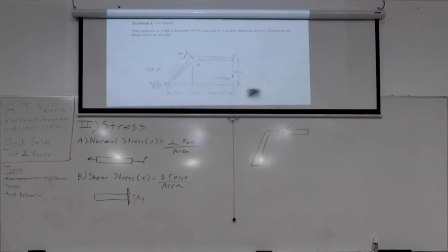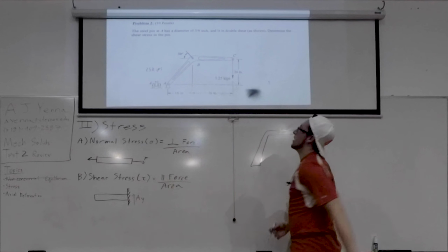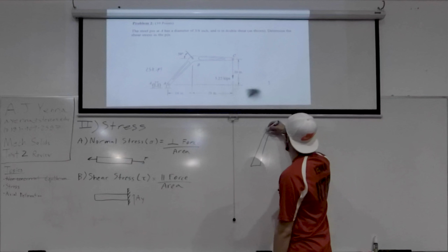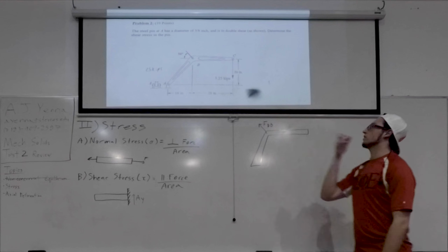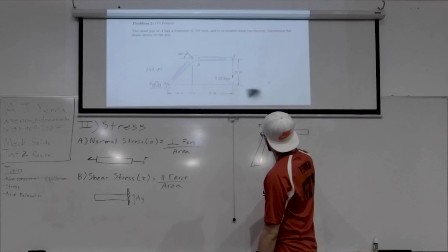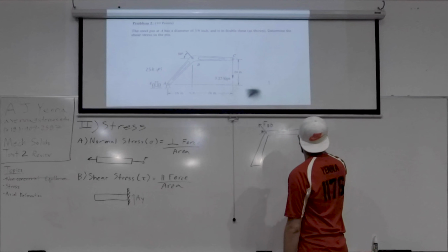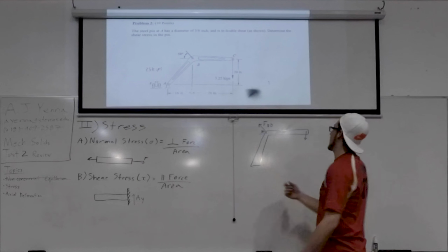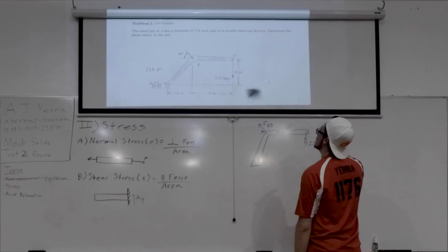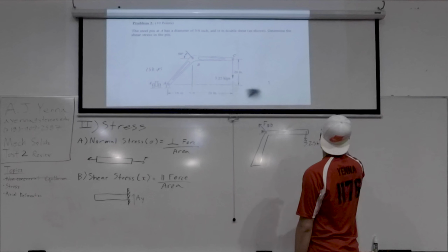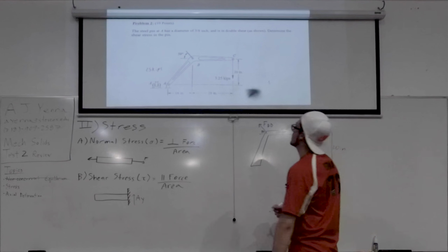Basically, it's a piece of string connected to the ceiling. So there's a tension at that point. The top up there was called point D before it got cut off. So I notated this guy, force in BD. That's essentially what it breaks down to. This guy is 50 degrees. It gives you the 3.25 kips. Just as a reminder, a kip is 1,000 pounds if it becomes relevant. Inches.